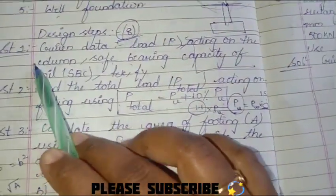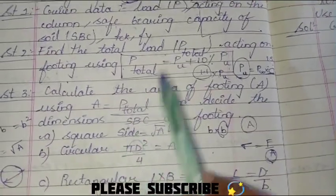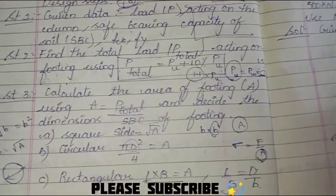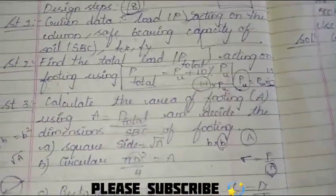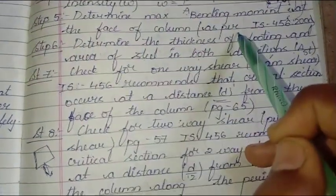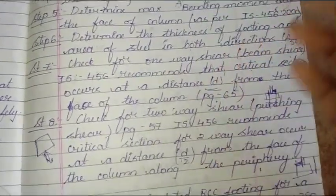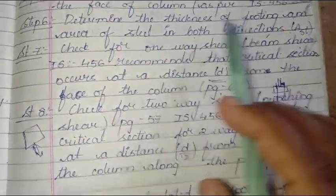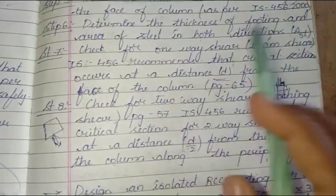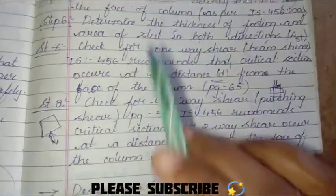Firstly, in step 1, writing the given data. Second one, we'll be calculating the total load that is acting on the footing, and next from that we'll be getting the area. We'll be deciding the shape of the footing first, and next comes the dimensions of that. And after that we'll be determining the net upward pressure intensity, the maximum bending moment acting, and depending on that bending moment we'll be considering all the factors, and we'll be determining the thickness of the footing and the reinforcement details. And once the reinforcement has been designed, then we'll go to the checks. If it is good, it's okay. If it's not, we'll be redesigning the structure.